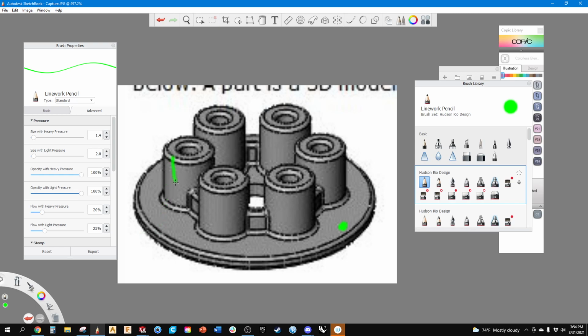Then next, what is next? Well, I've got another cylinder that's a circle, and it's a pattern that goes all the way around here. So what ways could I do this? Well, we already learned about extrude. I could do a sketch on this face and draw each one of these circles in the sketch and then extrude it.